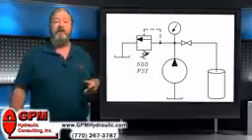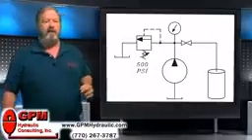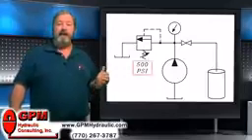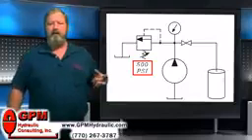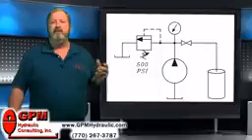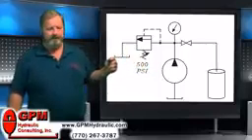Knob turner's name is usually not me. You know, who messed with the knob over there? Not me. Well, the last time that not me got hold of this knob, he set it at 500 psi. So in order to go through the relief valve, pressure must build to 500 psi. So that's the resistance in this direction.